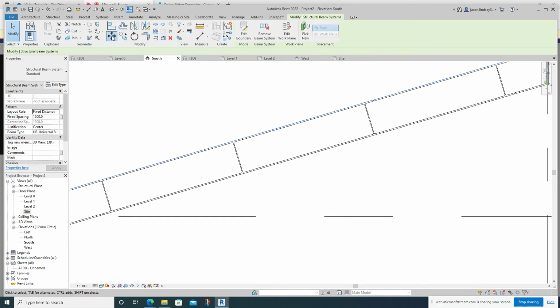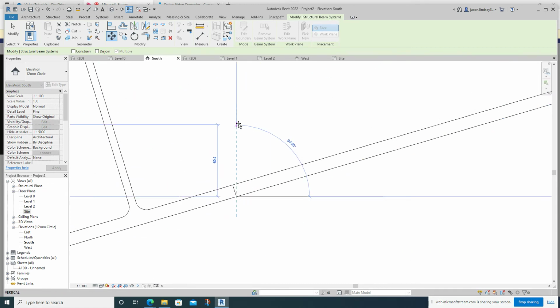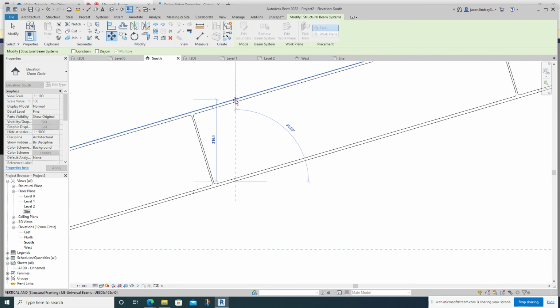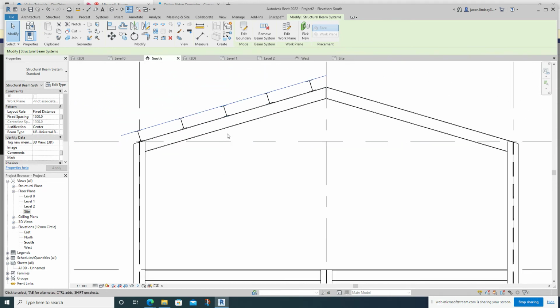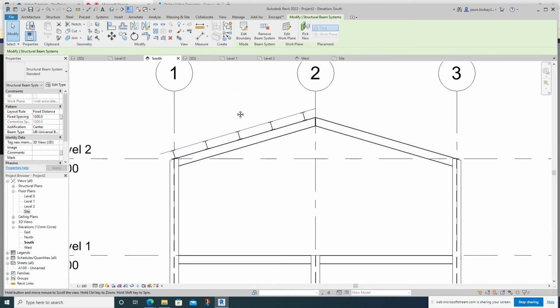So there's this one over here. So we click move, and I want to go from here, which is the bottom of the web of that particular beam. I'm going to go to the top. That's now shoved it directly upright. It's important you go directly upright and not perpendicular to this beam here, but straight up. And you can now see we're up the top there.